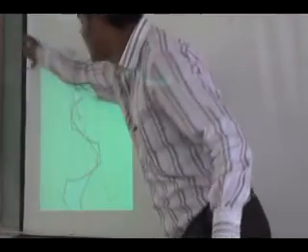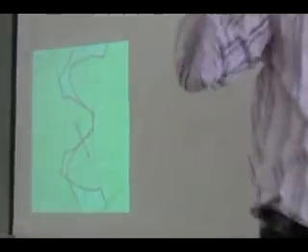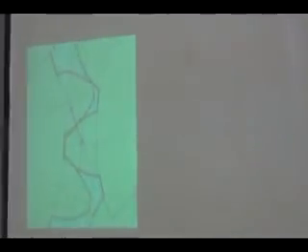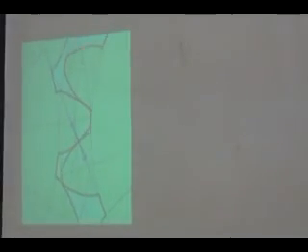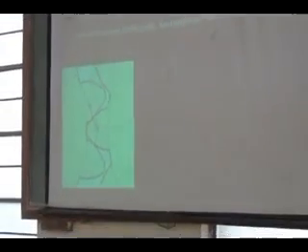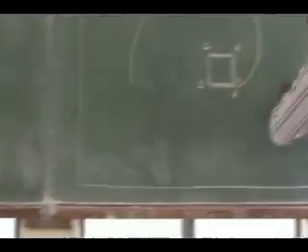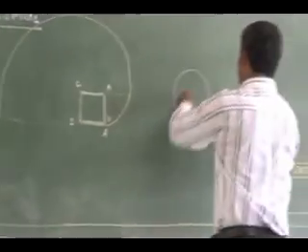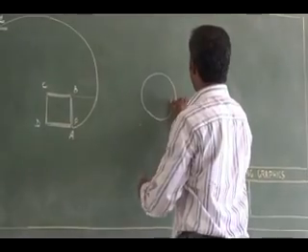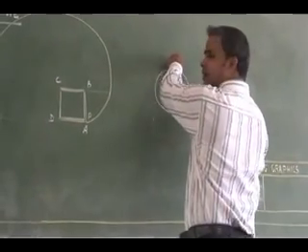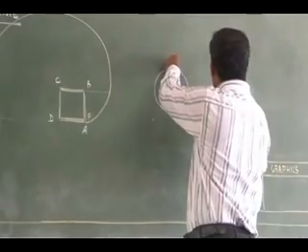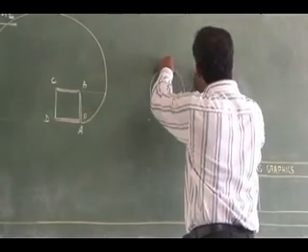This is the circle in this body, that is nothing but the base circle, involute of the base circle. So you can see that the profile. Suppose I have a circular, this is a base circle, okay. So I have a thread around this circle. If I open the thread, see here I have the end B. If I open the thread, keeping the thread tight, the thread will occupy these various positions.